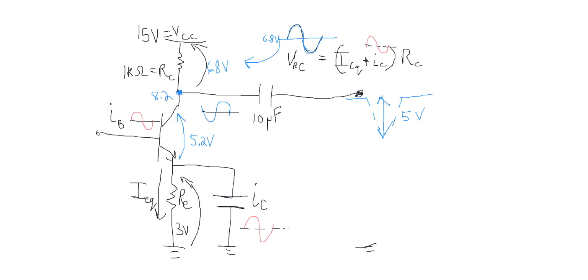Remember that RE's voltage is being supplied by this capacitor. It's doing the smoothing effect. It's discharging and recharging based on the variations it feels. So here we have the 0 condition, and now we're going to drop our base current so that we're choking this collector current. What happens here now?